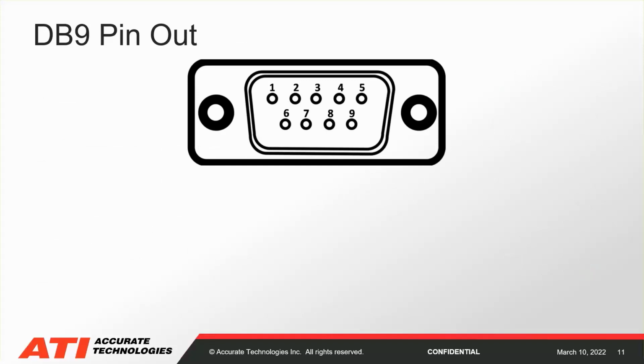Now, one of the first differences between CAN and LIN is the pinout for the hardware interface. Here you see a typical DB9, which is used on all of the Kvaser and ATI CAN interfaces. Here we see your typical CAN pinout, where 2 is CAN low, 7 is CAN high, 3 is ground, and 5 is shield.